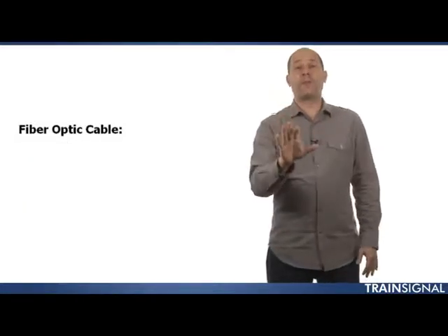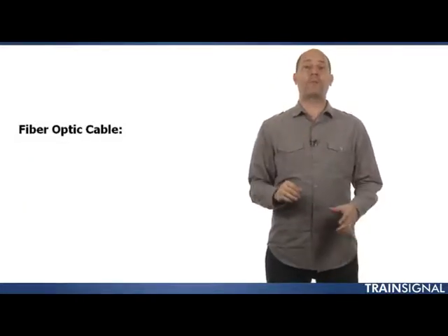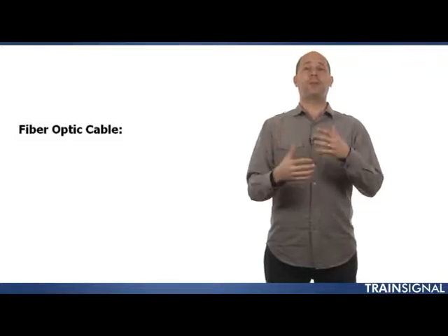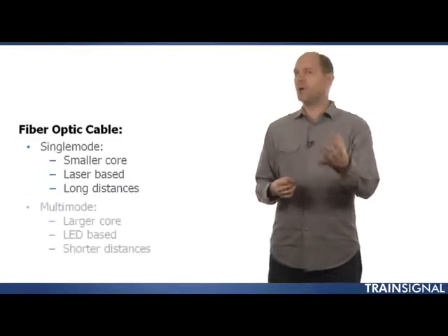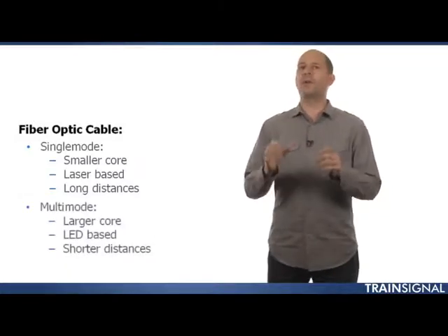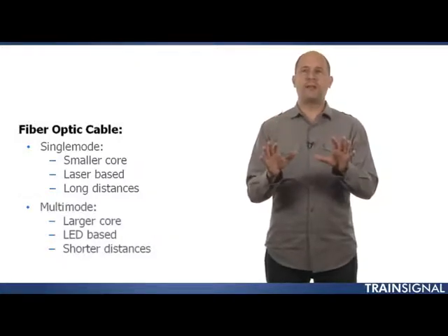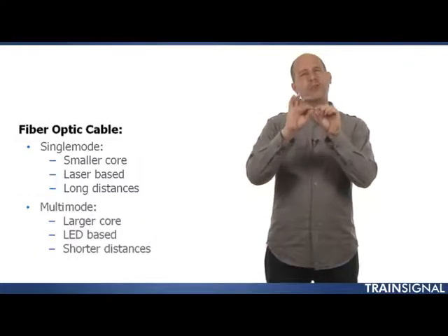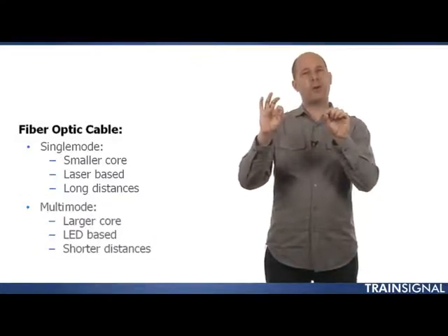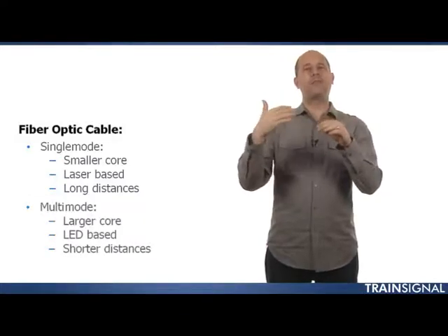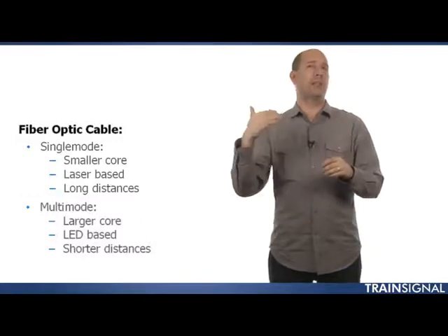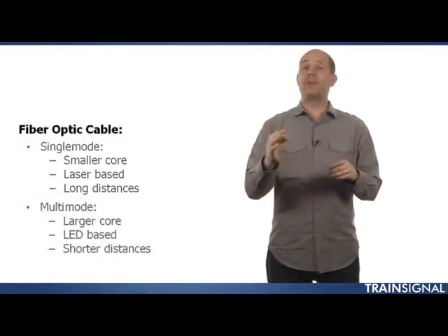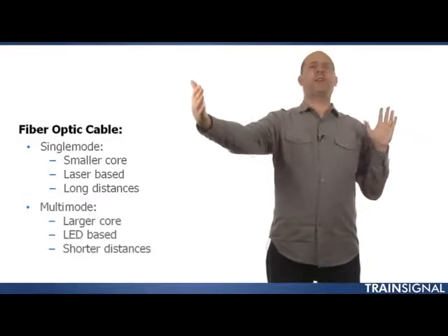Now, one more thing that I want you to know about fiber optic cabling is you'll hear it talked about with single mode fiber versus multi-mode fiber. I want you to know what the difference is when you hear that. With single mode fiber, you have a much smaller carrying core, and it's designed to work with a laser-based light, and the result is you can travel very long distances.